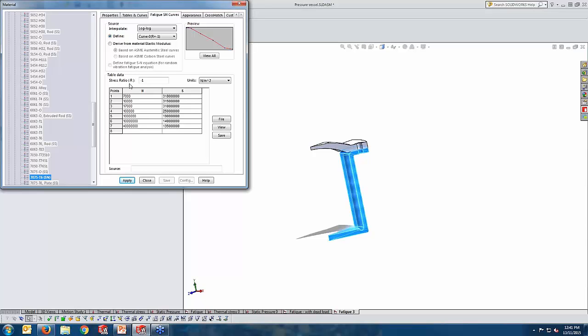and telling the stress ratio, which is the cycle as fully reversed here, as you can see, -1. It is interpolating by log data, and I can have up to 10 curves with a different alternating stress or mean stress range, but I've just entered one.